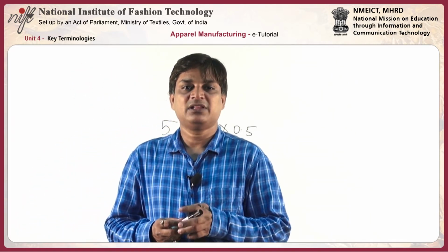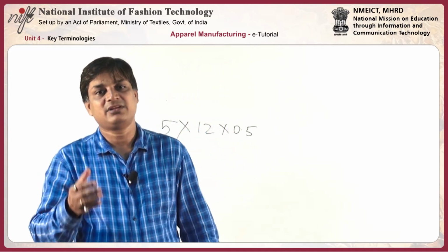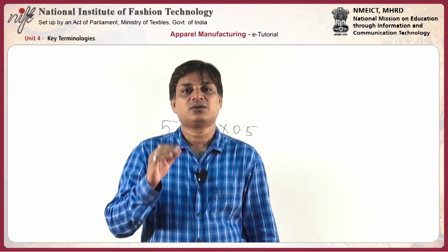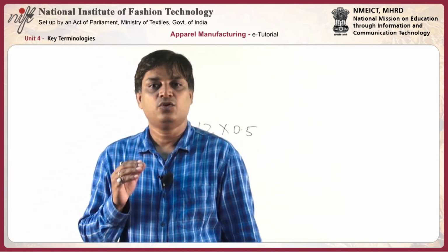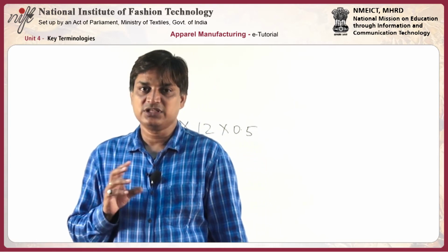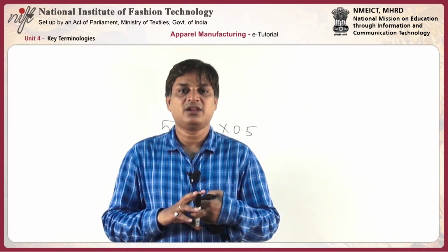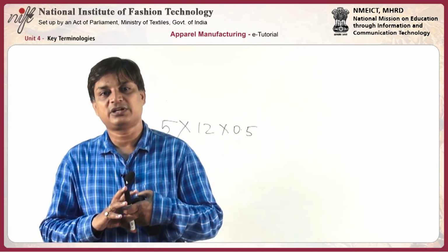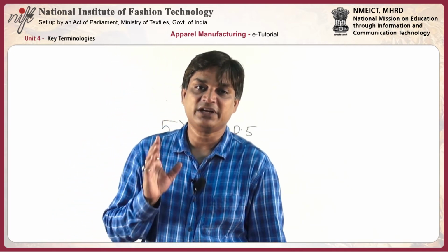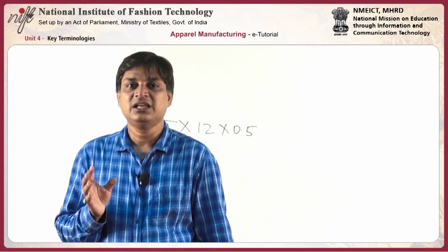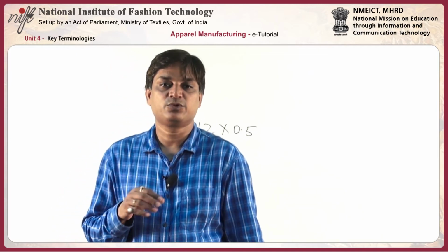With low WIP between the lines, garments have less waiting time and complete the product cycle in less time. If a large inventory is there, the goods waiting to be processed are kept waiting longer and increase the overall throughput time. So this is the WIP. If we have low WIP, we get low throughput time, and low throughput time permits better coordination between sales and production, and a quicker turnaround, which improves the cash flow.